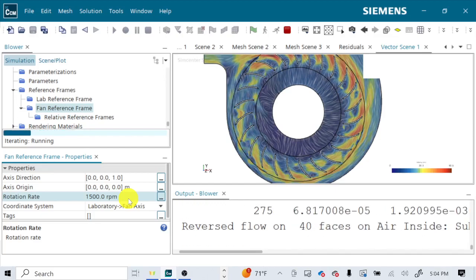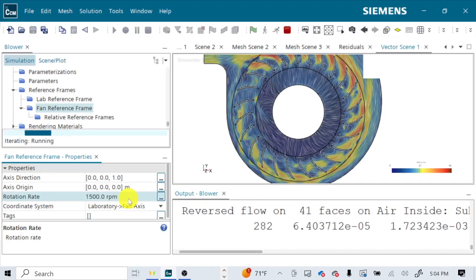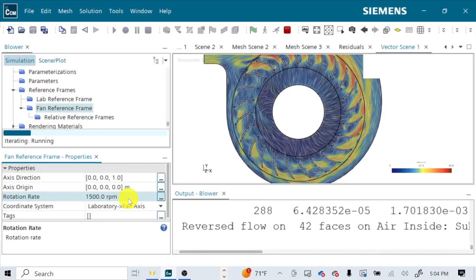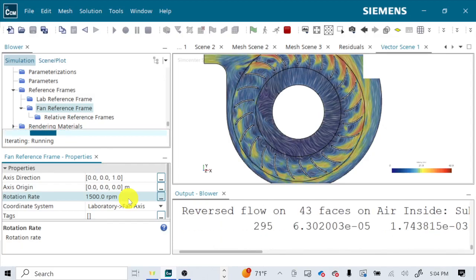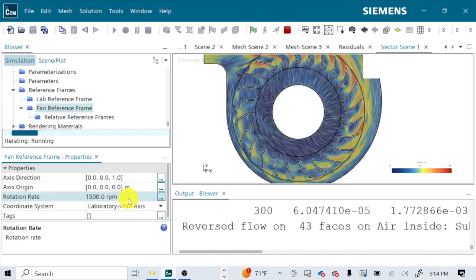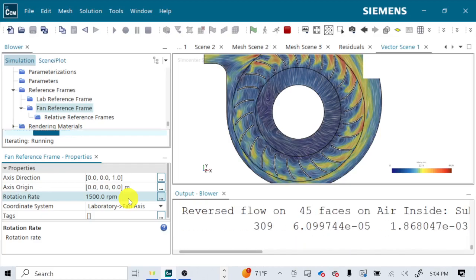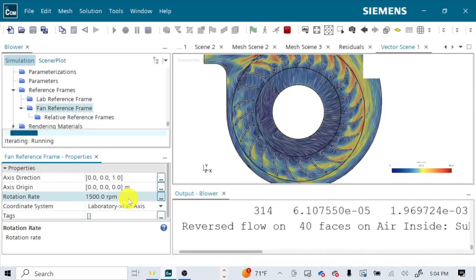Because let's take a fan, for example. If you try and move air through a filter, it's going to move a lot less air than if you just put it on the table and let it move air, right? So the filter is a case with higher resistance, and putting it on the table is an example of unrestricted or free flow fan performance. So principally, it will be this fan, but we'll look at a couple of different speeds, which are TBD.